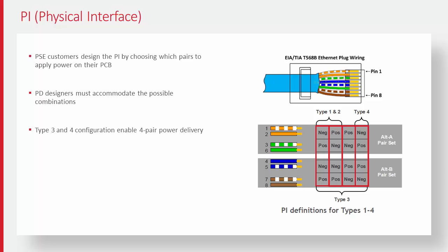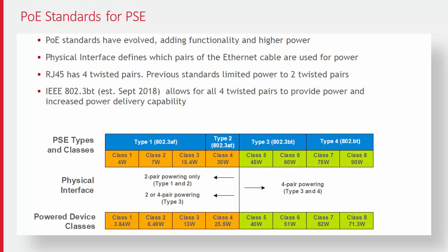So we've got twice as many conductors pumping current now. How do these new physical layer changes affect which PSE products we suggest to our customers? That's a great question. So the customers needing more power are going to have to move towards a BT item. The AT spec topping out at 30 watts is really just not enough for the connected ceiling or high-end power over Ethernet applications such as a very large pan-tilt zoom camera or even some workstations now being powered over Ethernet. Those things are going to need to move into that higher wattage range, and so that's going to move them from the AT spec to the BT spec. Did that answer your question?